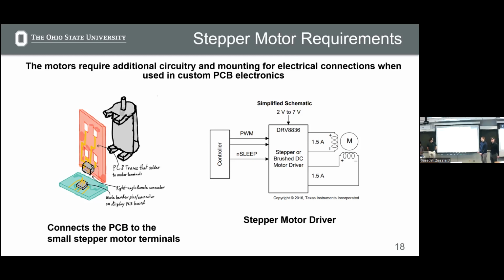But outside of only physical design, we also have plenty of electrical issues to handle as well. Motors are typically power-hungry devices that require a lot of current, and this is difficult for the Raspberry Pi to supply alone. So we need a device such as a motor driver that will help give the motors all the power that they need.